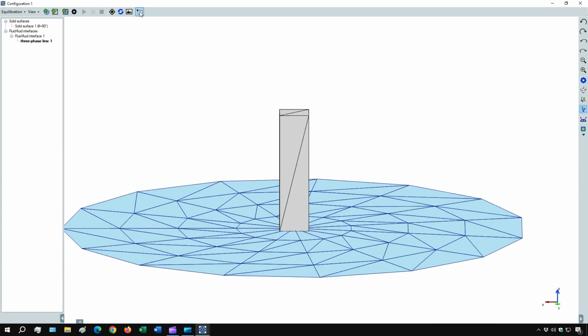By clicking this button, I can open the tool to check the 3D position of individual vertexes of a mesh. This can be convenient to decide how to translate opportunely the loaded meshes. For example, to translate the circular meniscus to the middle of the vertical pillar, I need to translate it in Z by 2 micron.